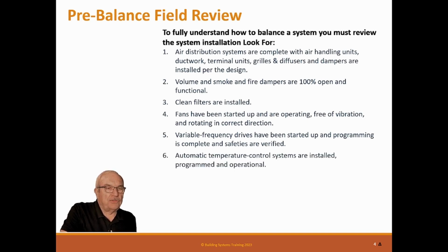Automatic temperature control systems are installed, programmed, and operational. Now, I know this statement is a perfect world. We never get on a job when the controls are 100% done, but they have to be done enough so that the air handlers modulate in automatic and all the VAV boxes can operate in automatic operation, and you can set them up so you can make set point changes in both the air handlers and the VAV boxes. If you cannot do that through the control system, then they're not ready and you need to wait.